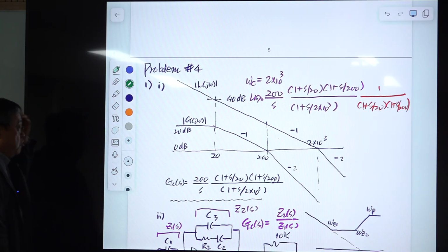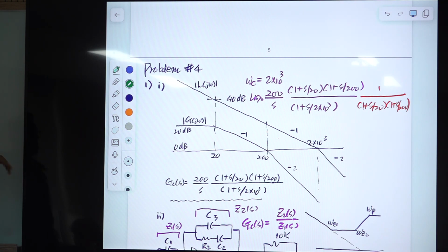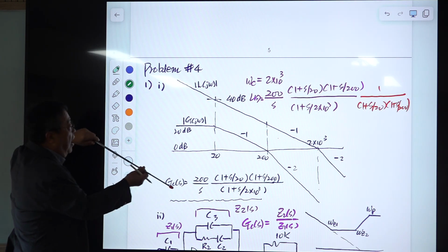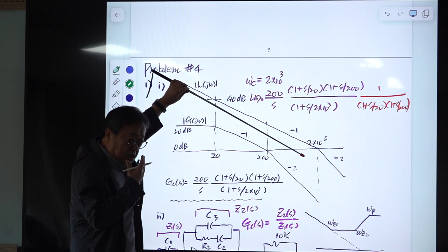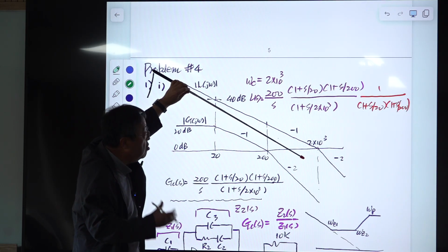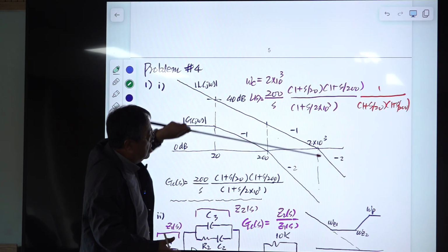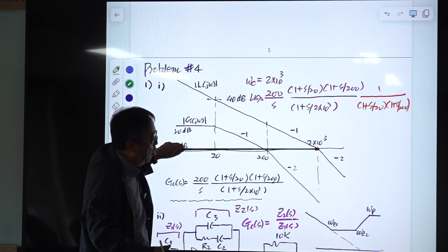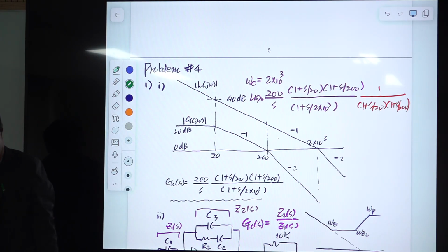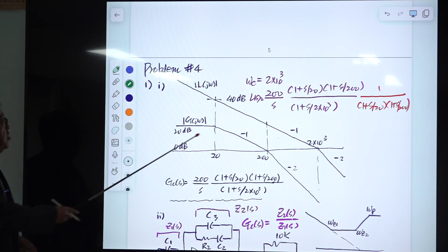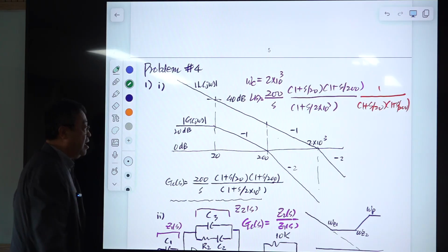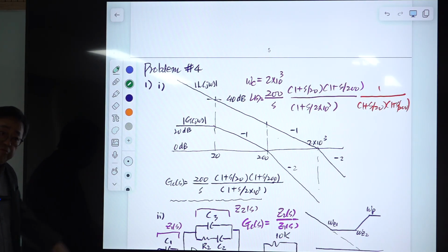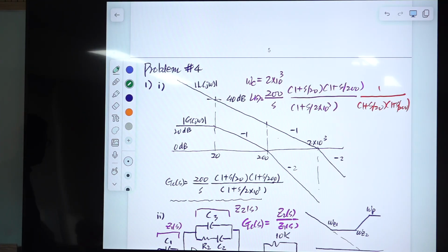And so the requirement is to start with the integration structure and maintain a -1 structure. It's the same as: select the simplest possible structure and locate the 0 dB crossover frequency at this point to obtain a 45-degree phase margin. So design the compensation to get this loop gain characteristic. Okay, it sounds formidable, very difficult, but it is an extremely easy task, right?